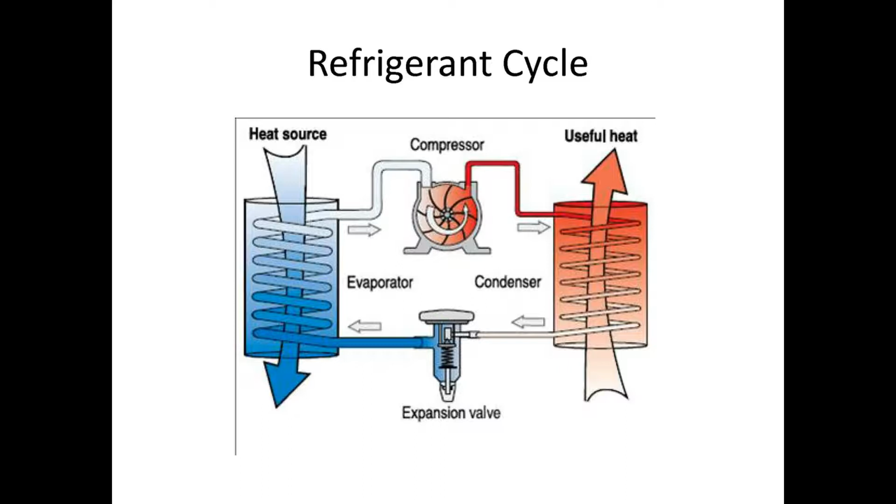Well, what it's doing is it uses a compressor and it compresses the refrigerant gas, a special gas, to a very high pressure. And when you compress something like that, it gets hot. I'm talking it gets about 140 degrees. So the fan blows the heat off out of the refrigerant gas